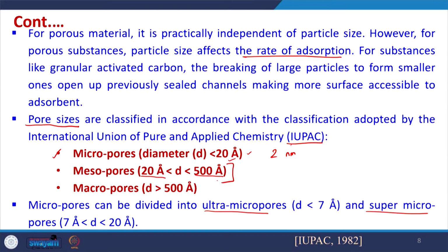But for liquid phase adsorption, for water or wastewater treatment, mesopores are very important. So, we always look for adsorbents which have more mesopores.